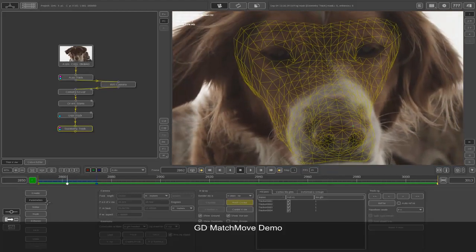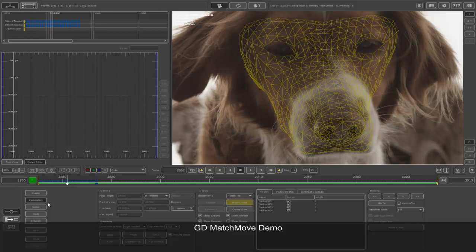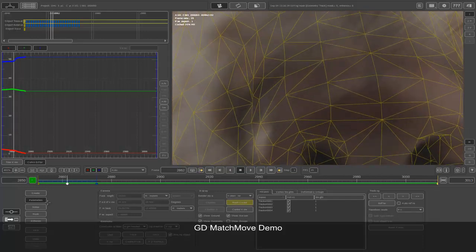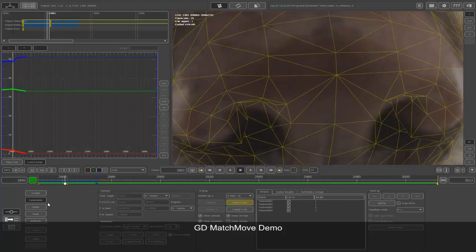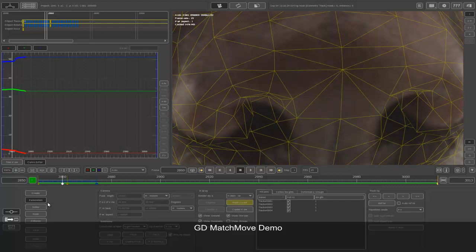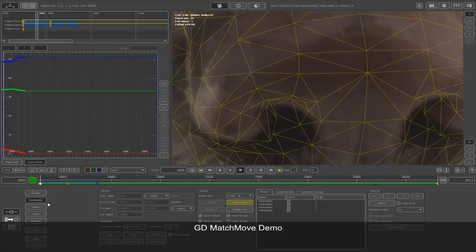So all I need to do is add in some kind of motion into the object to insert a keyframe. Also there is a curve editor where you can select translate and tell it to insert a keyframe, but I don't know why it never works, it doesn't create a keyframe. So the method we use is to take your pin, choose the mesh, move it a little bit off to the side and back, and if you move back you can see there's a keyframe created over there. So all we need to do is make sure the keyframe matches up perfectly.